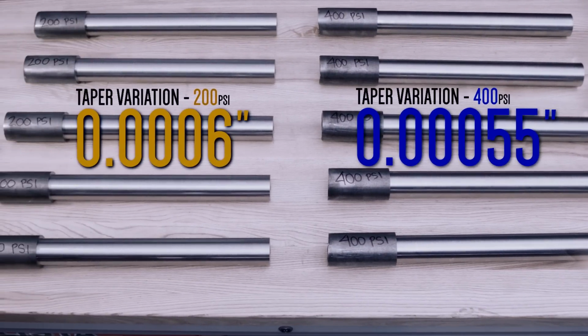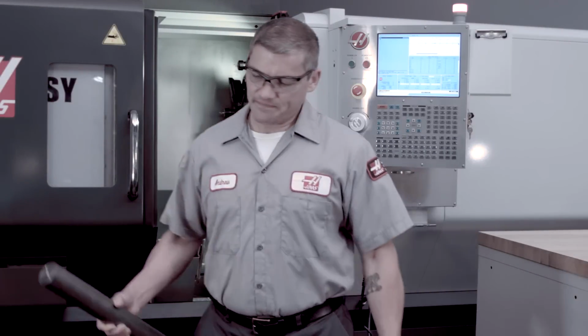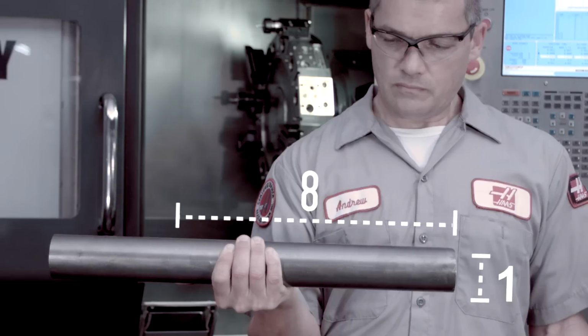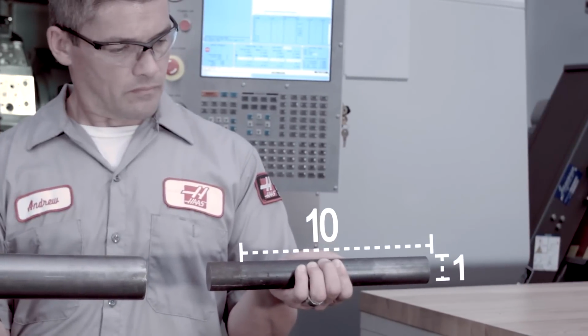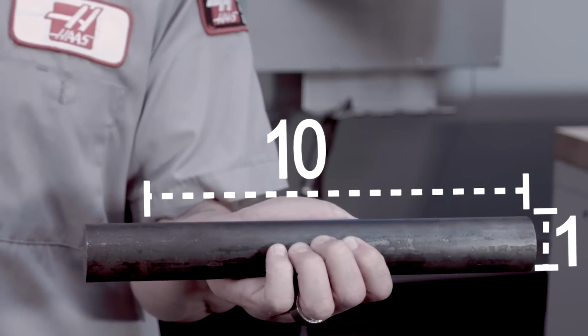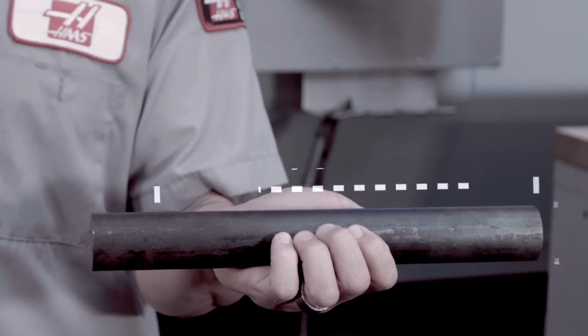Maybe this seems surprising, but we can clearly see that more tailstock pressure did not make the shaft profiles any more consistent. The large shaft that we just cut had a supported L/D of 8:1. But let's repeat this test on a different shaft to see if this trend holds up. This shorter shaft has a supported L/D of about 10:1.